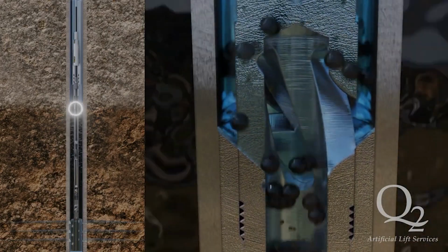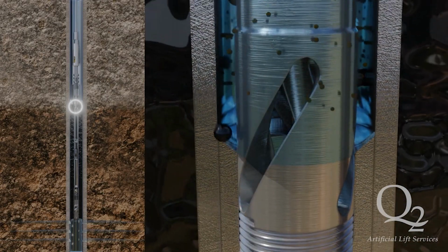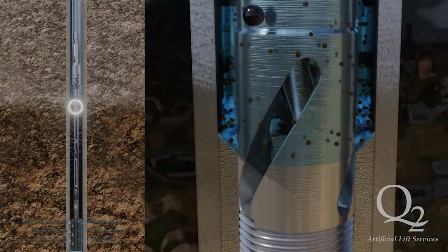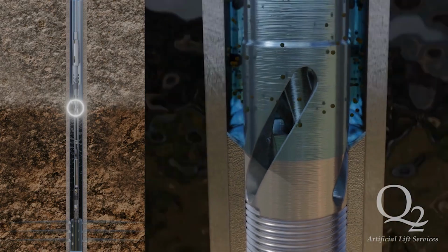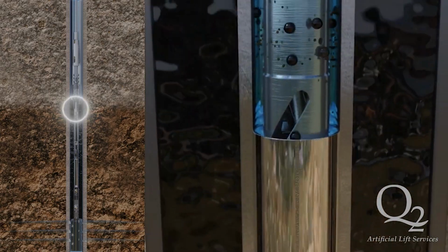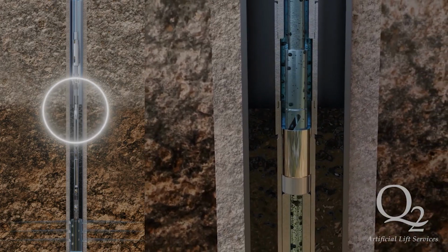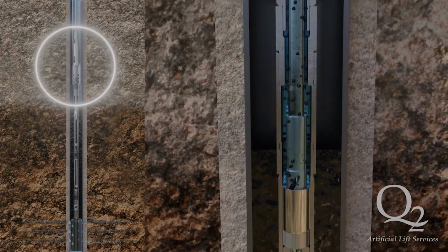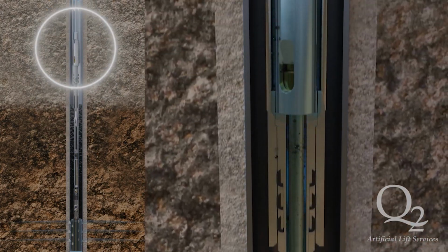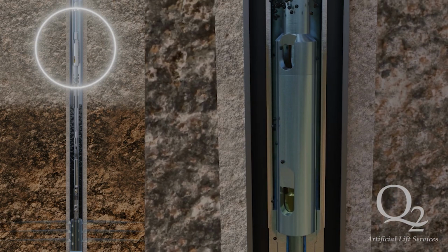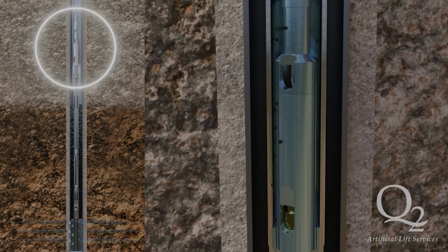The discharge ports in the sand twister are designed with the same angle as the Q2 flow cage, maximizing velocity. Sand is moved in the top portion of the barrel chamber through the discharge ports of the component. The component is also designed with a minus 2 fit with a beveled edge, disallowing sand to move alongside the plunger. This beveled edge will also direct sand back through the ports into the ID of the plunger. Sand is then moved through the rod guide into the tubing column.